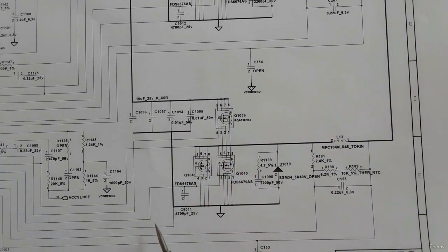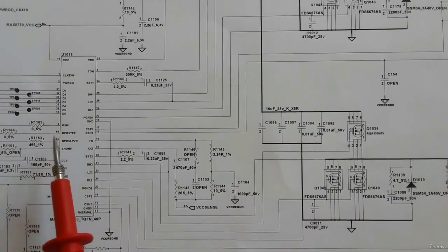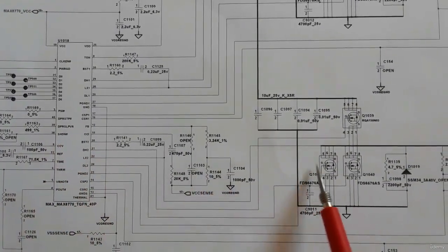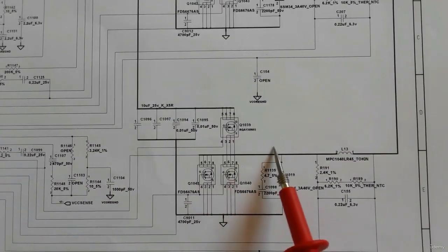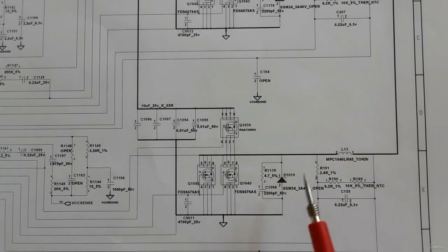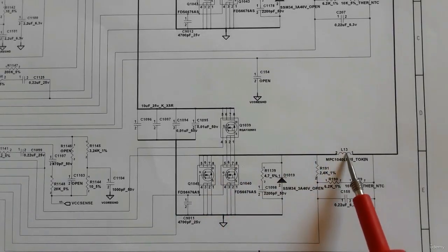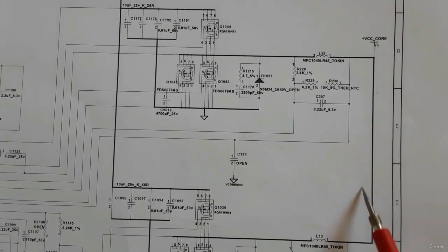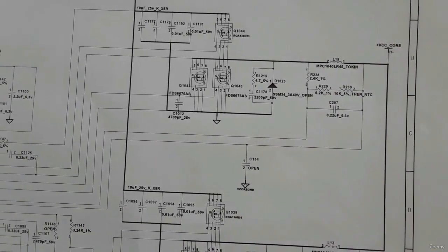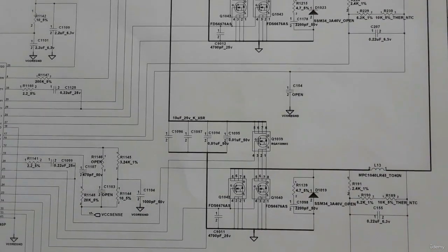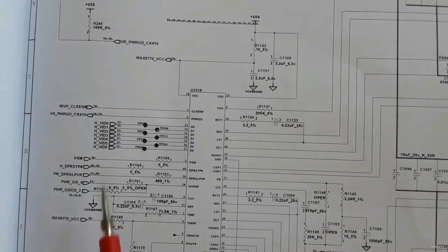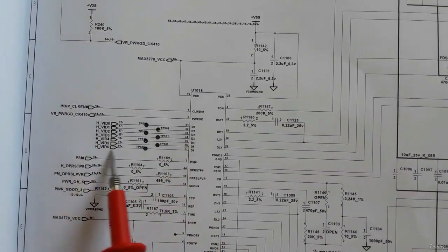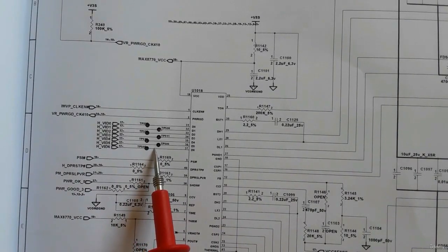Okay, so this is the power management IC that generates the control signal for all MOSFETs. So this is the protection diode that is responsible to protect the CPU if there is a high tension or a high current. And the purpose here in this circuit is to get the plus VCC core for the CPU. And as I told you before, every CPU has 8 IDs. Based on the signals, the power management IC knows the value of the VCC core.